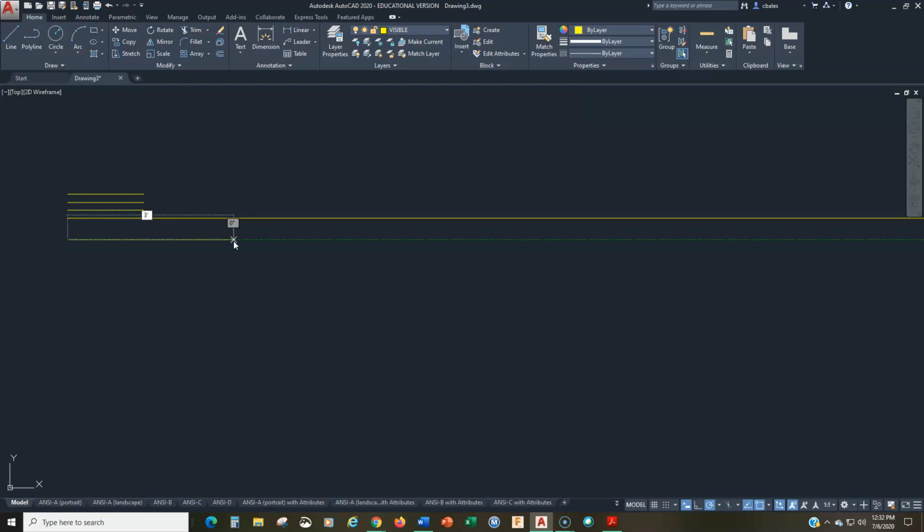Now, what do I do with the 6? How do I enter the 6? There's a couple of options here. The easiest option is just to type in 6. So 3 apostrophe 6. No space, no double quotes. Enter. And there we go.